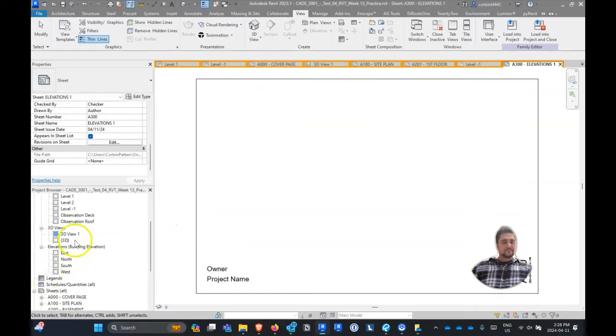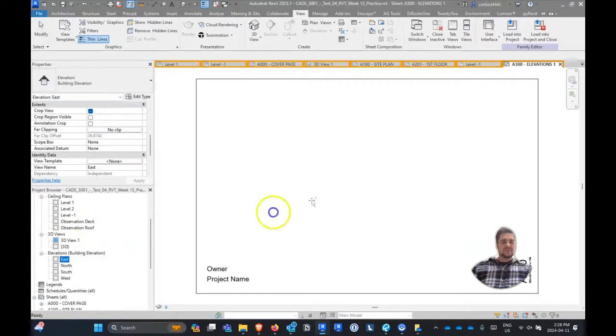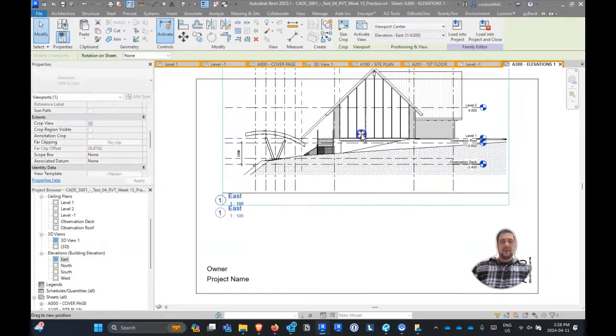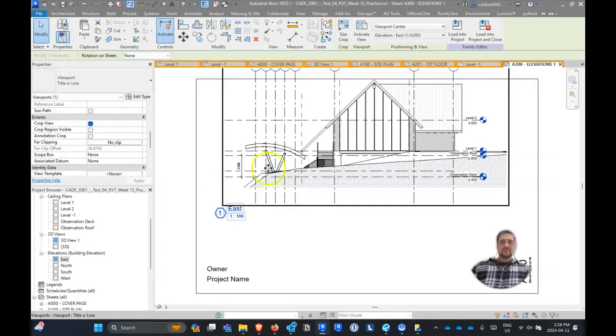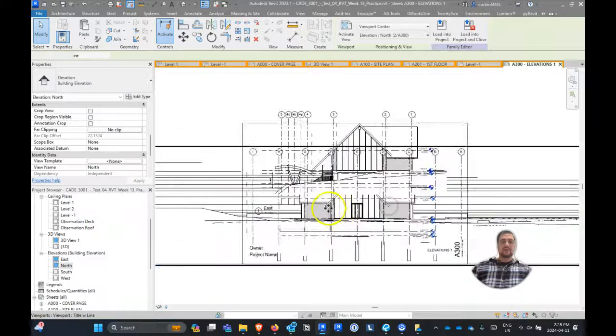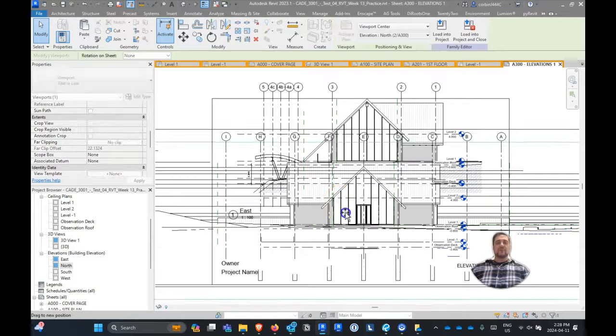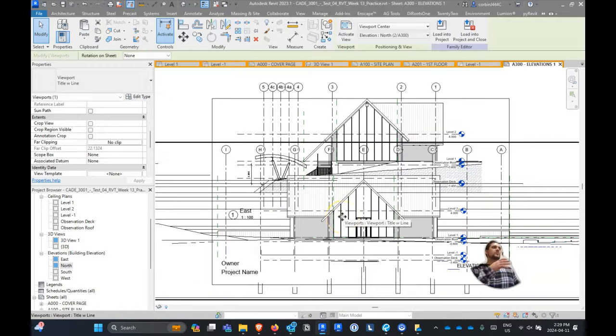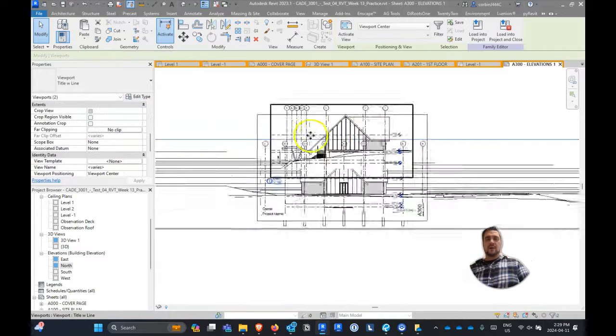And so elevations, again, we'll do 2 elevations maybe. These elevations are pretty tall, actually. My recommendation usually is we do 1 elevation in each direction. So like we don't do east-west, we do east-north. And the reason why is you might have 1 long, 1 short, and you can have some room for notes or anything else on your drawing. So we kind of use opposite or non-corresponding ones.